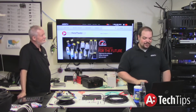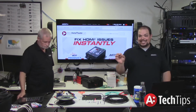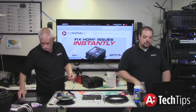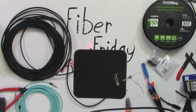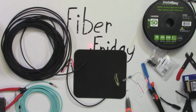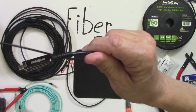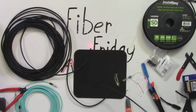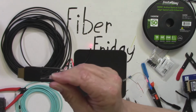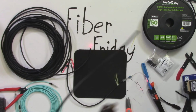He's asking, are the ones with the detachable head shells, the IB-HD AOC-D cables, able to be upgraded to greater bandwidth? No. And the reason for that is the electronics that actually handle the signal are built into this portion of the cable. The head shell itself is literally just an adapter to go from a micro HDMI to a full-size HDMI.